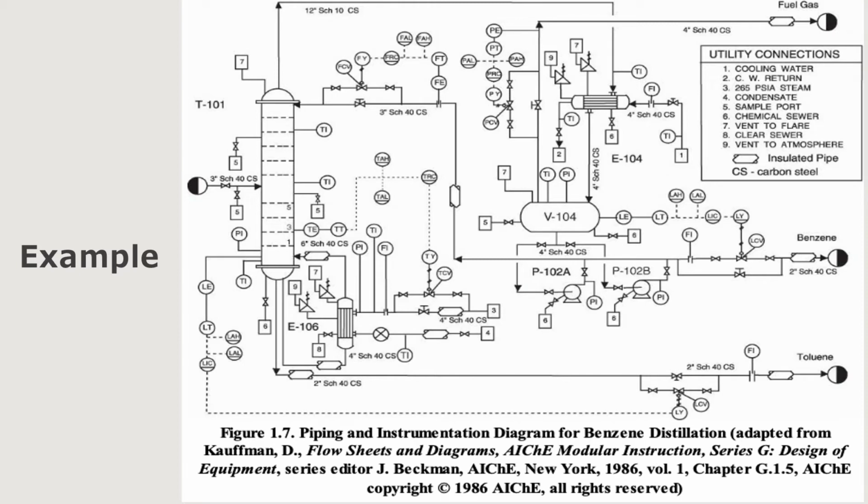For example, the temperature systems that control the distillation tower, or the level systems to control the vessels, as we can see in V104, or here in E104, where we can see another temperature arrangement for this heat exchanger. These systems that control input and output signals are crucial in chemical processes to make the operations easier to control, safer, of course, and consequently to have better functioning.